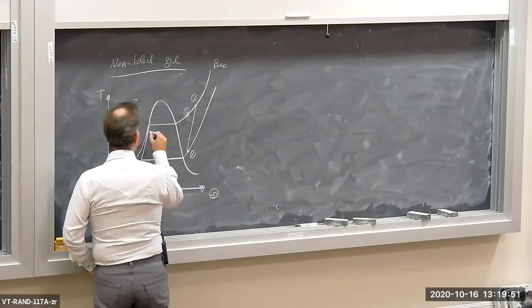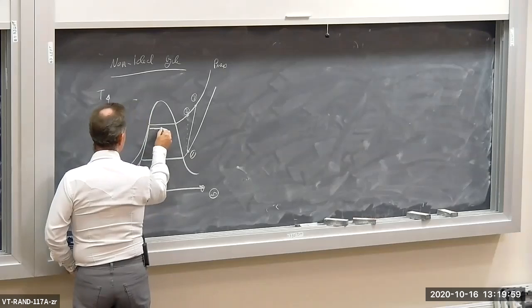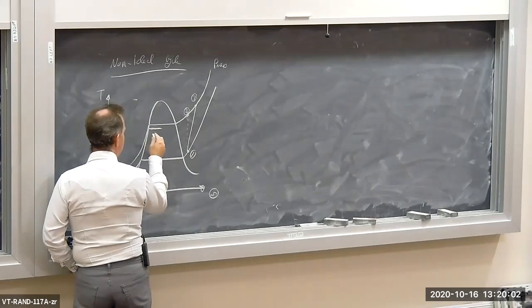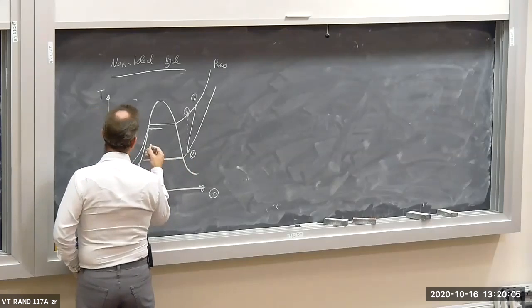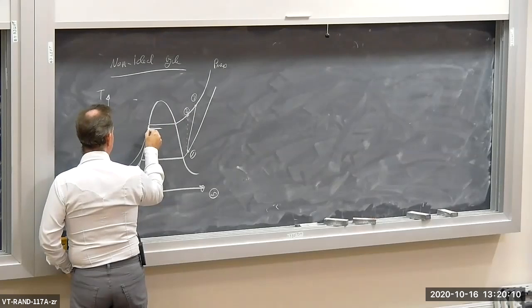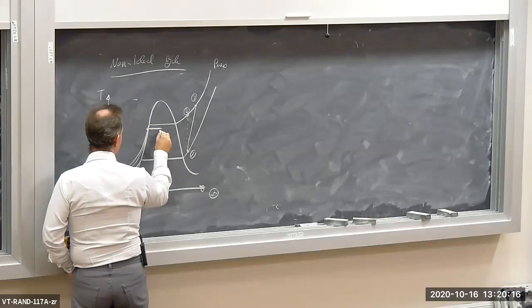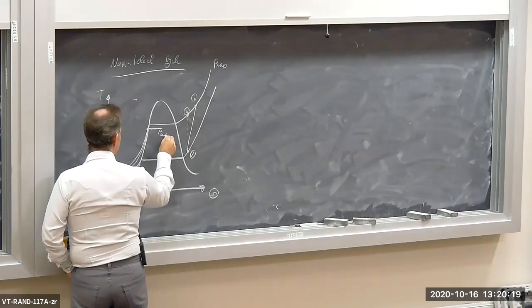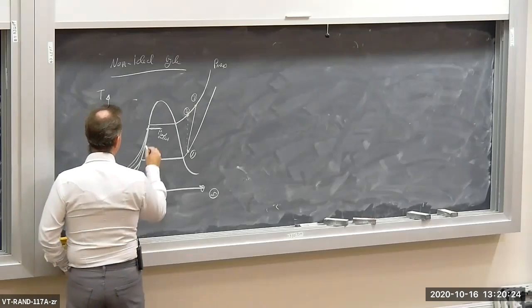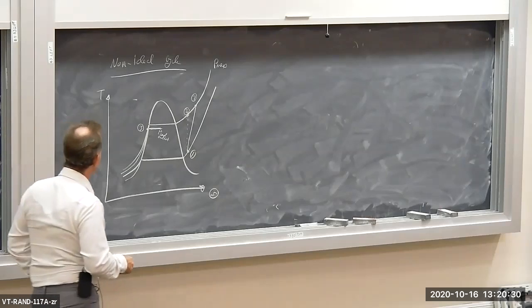We could have a pressure drop in the what? In the condenser. So the condenser is like a radiator, it's a heat exchanger where the fluid is turning from a superheated vapor into some kind of a liquid. So we could end up at some lower pressure. So we could have P condenser outlet. We could have a pressure drop in the condenser due to friction. And so state 3 might look something like this.